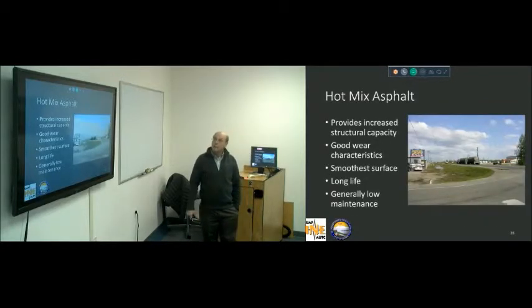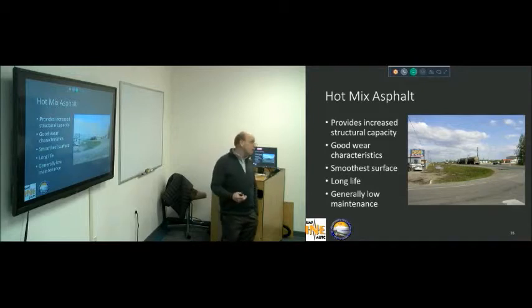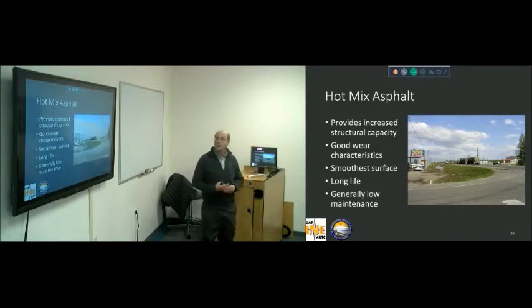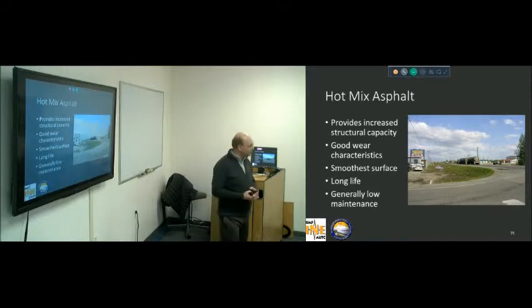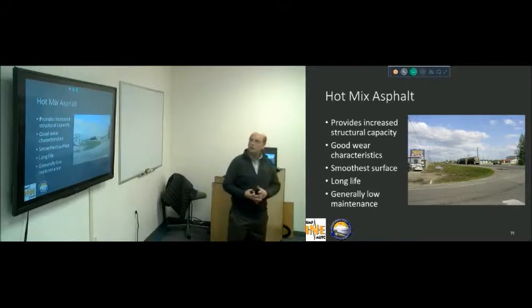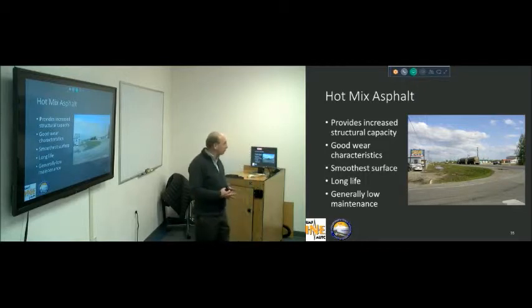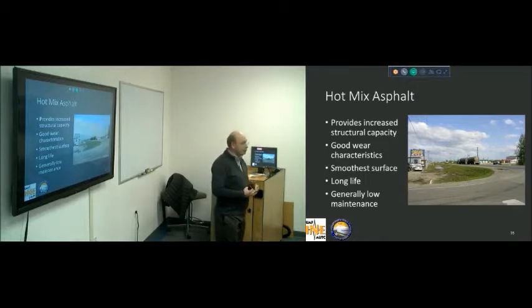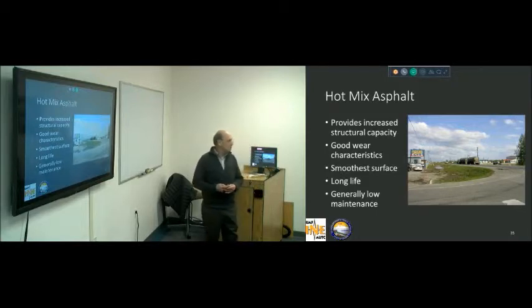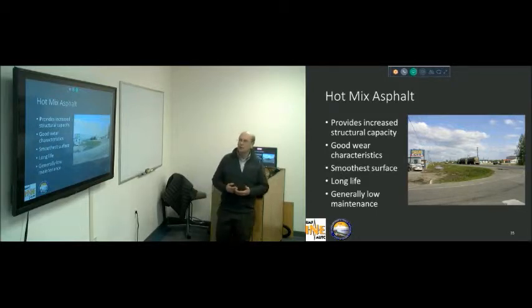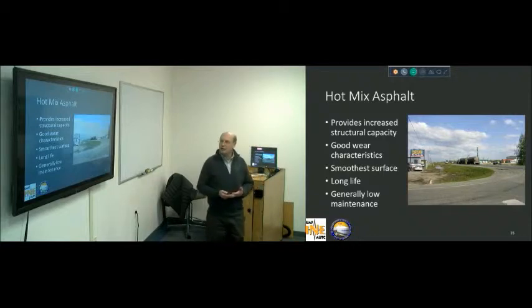Hot mix. It provides increased structural capacity. In other words, it adds strength to the pavement, unlike a chip seal. It's got good wear characteristics if it's designed properly and the mix is put together properly. It's got a smoother surface and a quieter surface than surface treatment. That's one of the complaints people have about surface treatments, is they tend to be a little bit noisy. There are some things you can do to reduce that, but in general, that's the case.